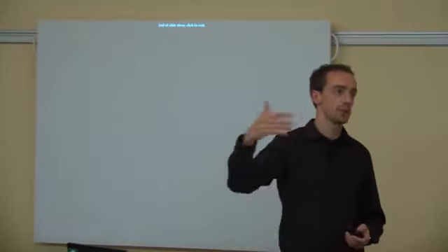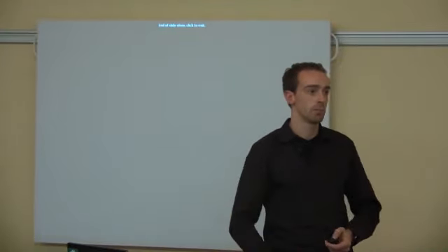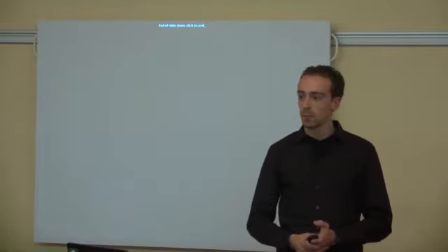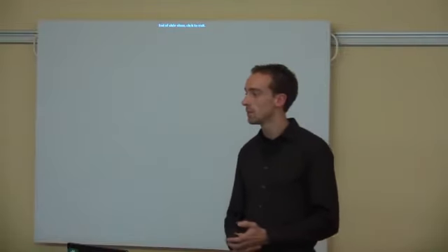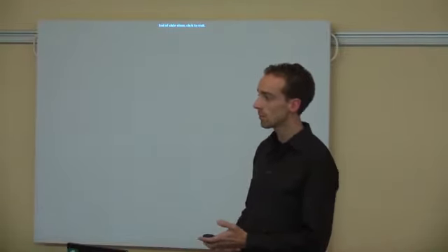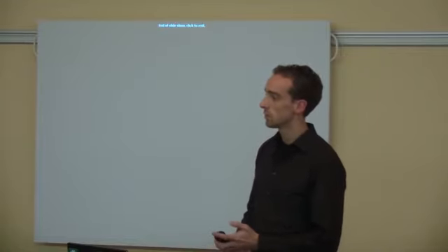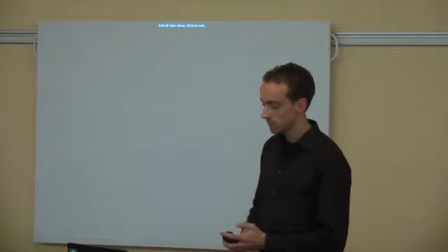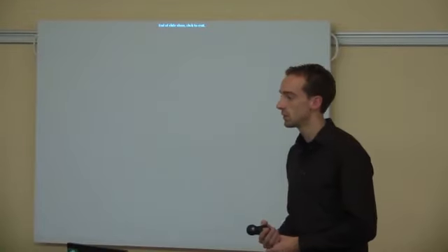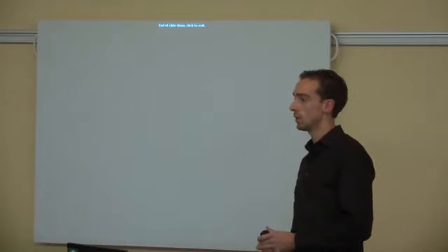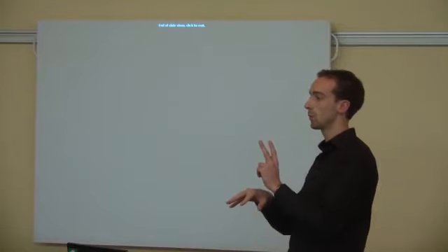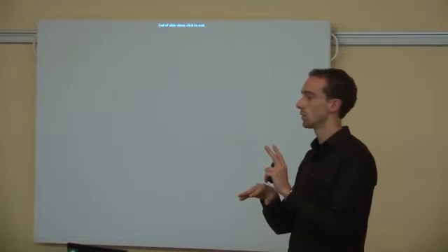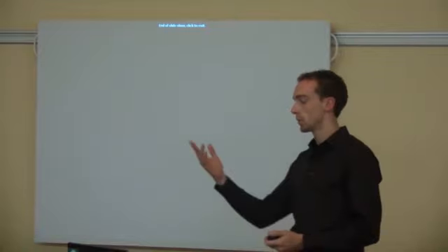But then the question is also what distance do you really want to detect? Because on the other side of the field, there are also robots over there who can tell you where the ball is. Do you also use the OmniVision camera? So you have 2 cameras? Yeah. Okay, but then you can generate stereoscopic pictures, so you have that information too. That's true. We have thought about it indeed, but not implemented it yet. That would be very interesting. The only thing is that as long as you know the exact angle between the cameras, you have a very reliable measurement, of course. But as long as one of the cameras is slightly rotated, then you're off all the time. But the same goes for the Kinect sensors, of course.